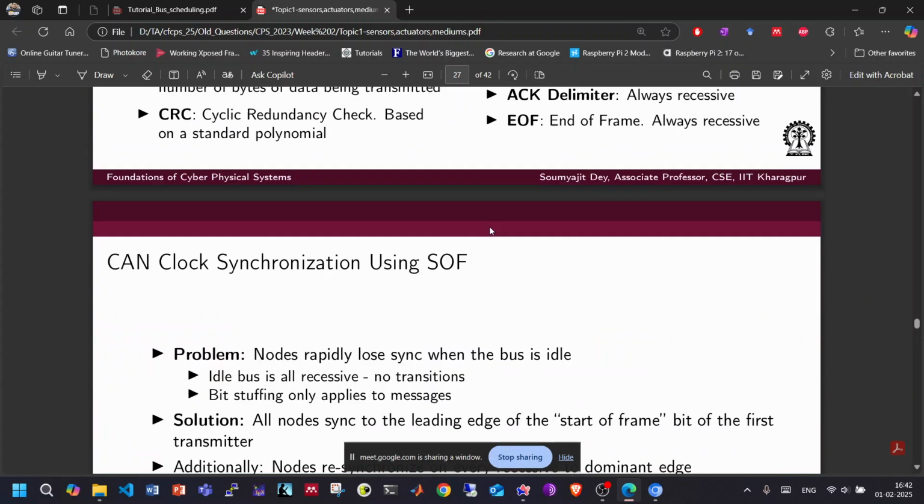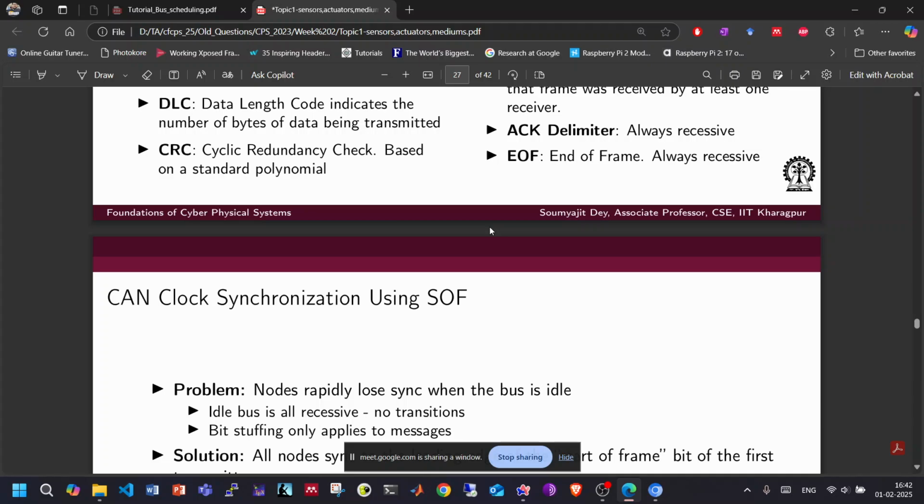Anyways, what I mean to say is, in order to synchronize, there are 0 or dominant bits in between this continuous 1. But what I am trying to say is, this works like an AND gate. This twisted pair of wires, when used in a bus architecture, behaves like an AND gate. That is why the dominant state is marked with 0 and the recessive state is marked with 1. This is the encoding that we use while we are using a CAN network. Make sense? This is the ideology. The idea made sense, right?